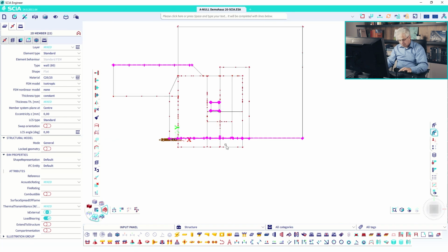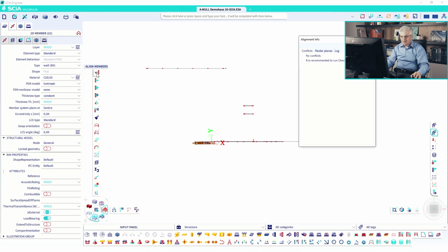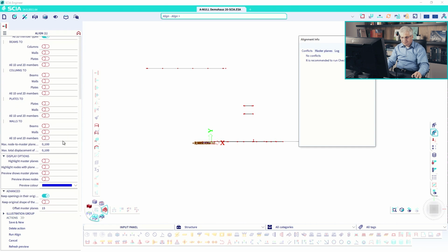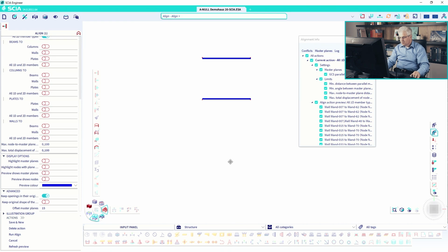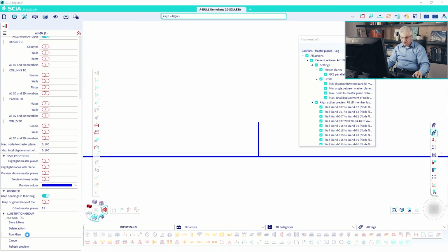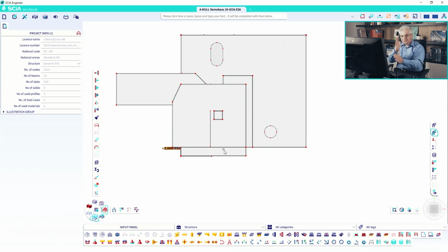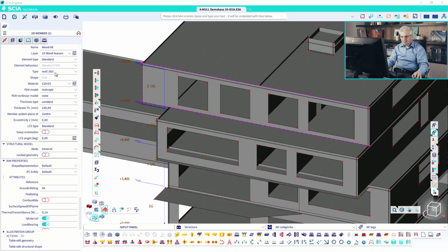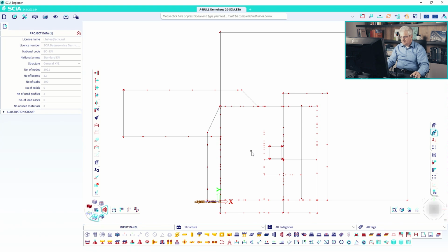correct here. Control E, select only these walls, select them, run the alignment. It's saved also with these distances 10 centimeters. Simply check the alignment, so they will be moved to the inner wall, and here the outer wall will win. Run alignment. So now we have walls, and you see this, there was some short wall. Okay, Control Q. We have walls really nice in one plane, and if you want, you can check it. Control E and go to the top view, and then everything is okay.